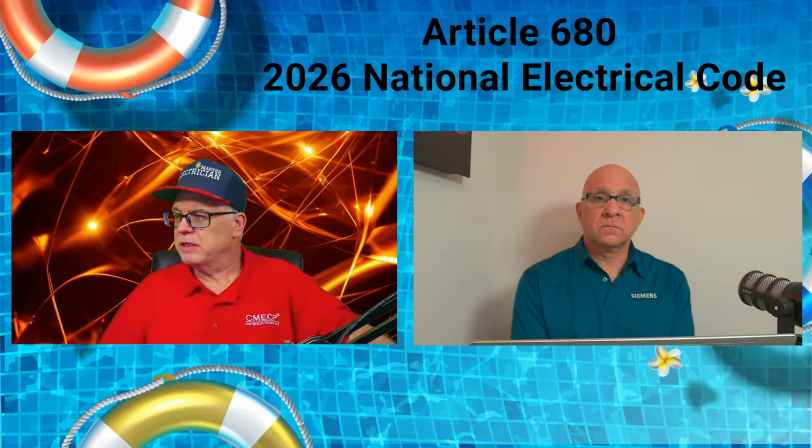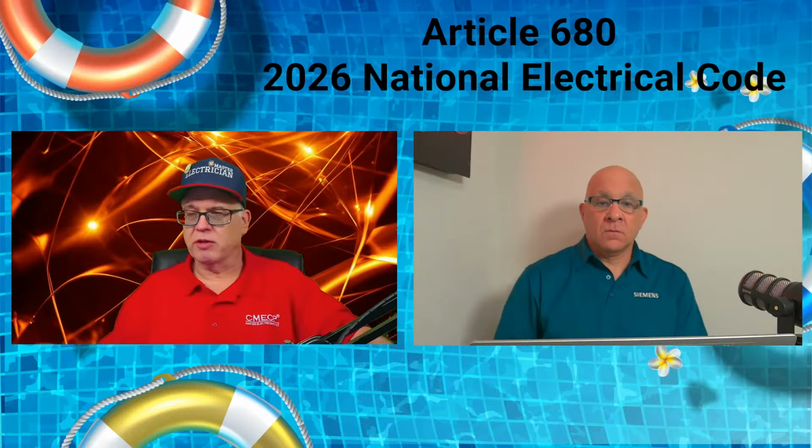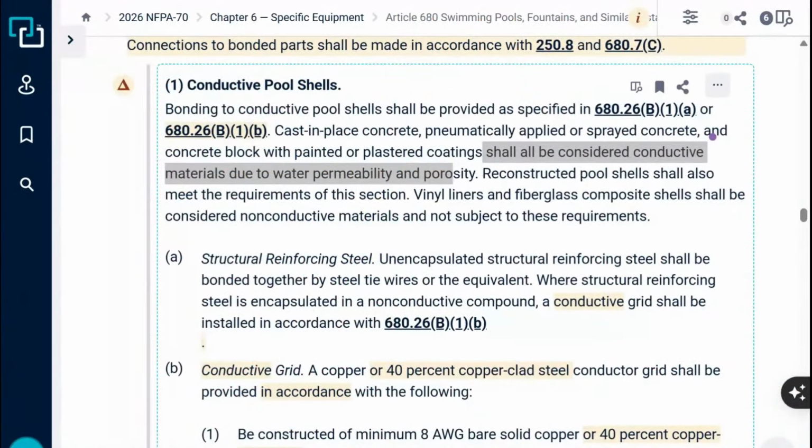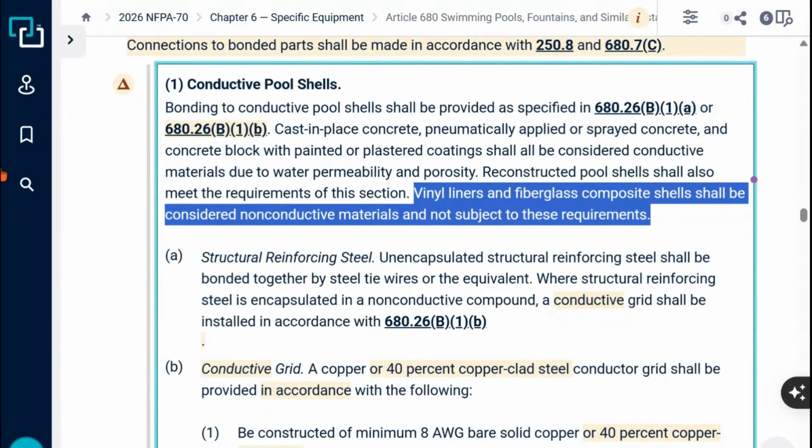So now, once we establish that it's a conductive pool shell, we have to establish what is not a conductive pool shell. When you look at the NEC, it makes it clear right here in the last sentence. It says vinyl liners and fiberglass composite shells shall be considered non-conductive material and are not subject to these requirements that we're getting ready to talk about. Now, that doesn't mean that the perimeter doesn't apply. This is exactly, just when it comes to conductive pool shell. So we have to be careful as we maneuver this language.